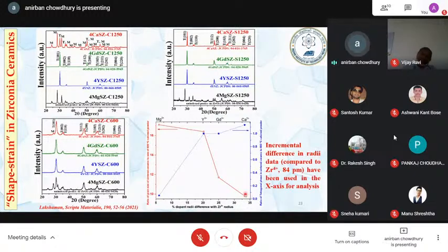And when you control this size in the sintered body, you can now improve the tetragonality. Magnesium has the lowest control. That's why magnesium has the lowest amount of the tetragonal phase developed. Once you have more control on this, when you can keep this size at its minimum, you can have the maximum amount of tetragonality. So the blue one is the ratio of tetragonal phase from the ceramic to the 600 degree C calcined powder. So you can see that now this is increased.